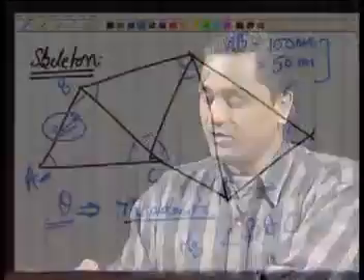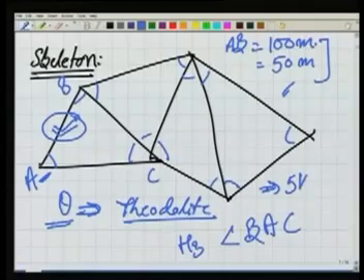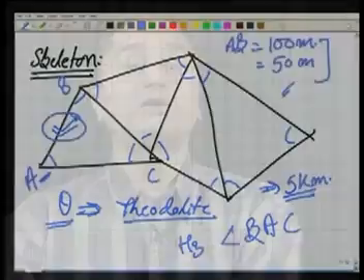But many times your base length may be of the order of 5 kilometer. This is what may happen, 1 kilometer, 2 kilometers. You are doing the triangulation in a hilly terrain in order to cover an area of 30 kilometer by 30 kilometer. So your base lengths are of 2 kilometer length. How to measure that base length if you don't have the EDMI with you?